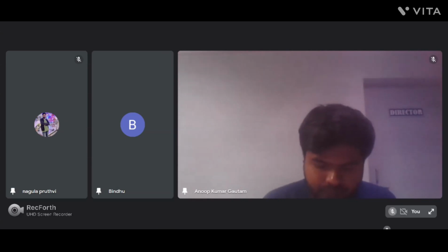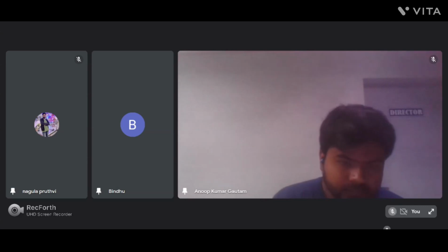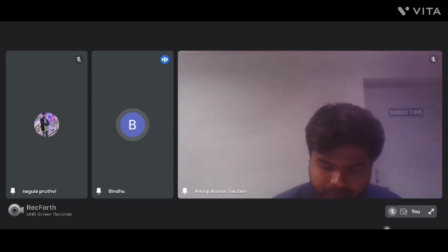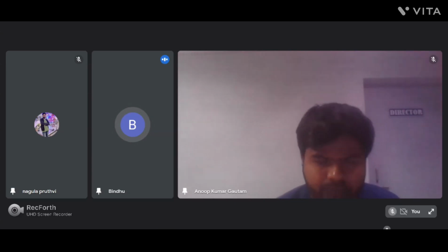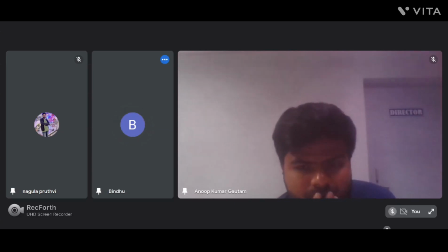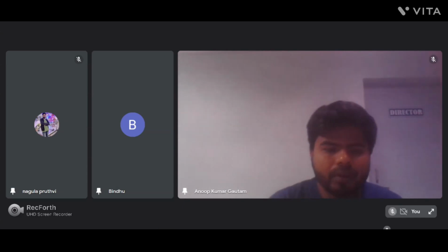Only 2 people. I got answers only from the 2 people. Okay. So Bindu, why are you thinking that this answer is like that? Can you explain? Since we are using blocking statements here, they execute sequentially, that is one by one. So first of all, A is transferred to Q1, and then after that Q1 is transferred to Q2. So ultimately, Q2 has A value, so there will be only one block.